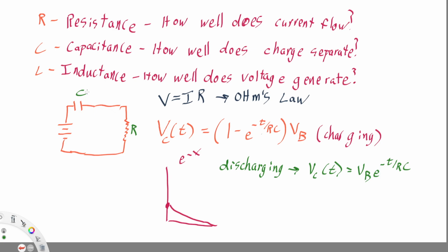When I taught this lab, by the way, I used to say that this lab is the modem restarting lab. So how many people have ever called into Cox and said, you know, my internet's not working, and the first thing they say is, turn it off, wait 30 seconds, turn it back on, right? Has everyone had that experience? Why do you have to wait 30 seconds before you turn it back on? So the capacitors can recharge. Well, yeah, so discharge, yeah, that's exactly right.